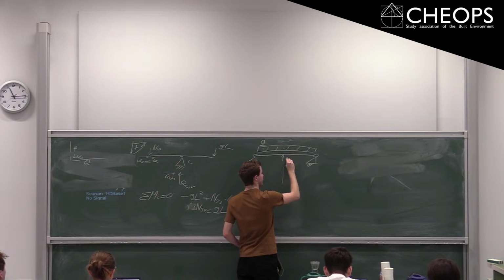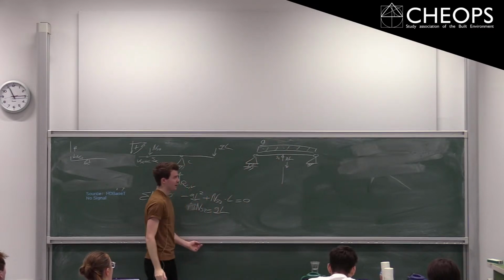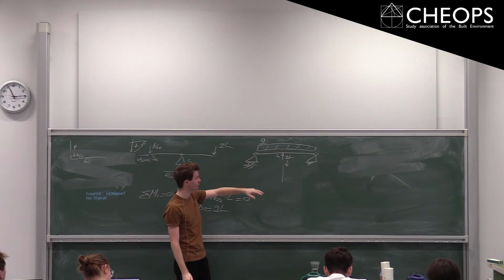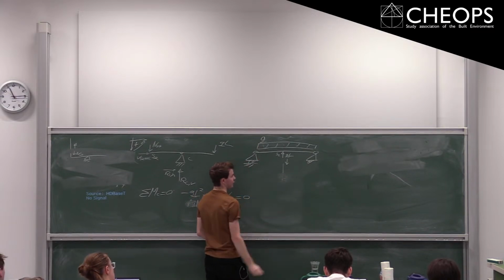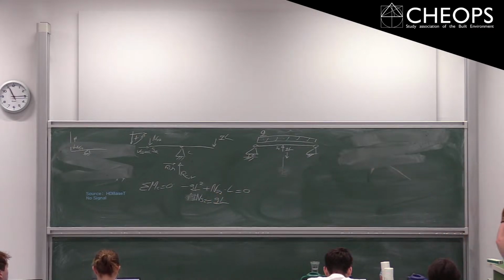So this is simply QL. And this is then S2. And now you can see already two cases arising, right? So the distributed load, as well as the vertical point load. And you combine these two to find the displacement in the middle. And actually, the next step is simply using those standard beam equations. So the first one is the distributed load.